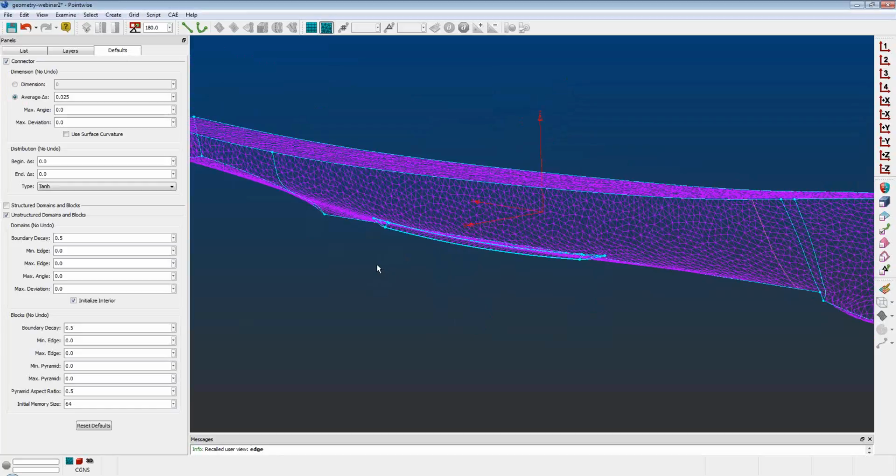So the general approach with our software, Pointwise, is, in this case, I actually have the default panel open in Pointwise. So what we do is we just say we're going to set an average spacing, or if you want, you can fix the number of points that are going to show up on the grid curves. And there's some more advanced parameters below, but for the most part, as a first step, you go ahead and fix your geometry, or maybe you don't fix it, you use the fault tolerant approach, but you put a mesh on your geometry, and generally as a first pass, it's going to be relatively uniform. Again, there are some advanced tools for creating non-uniform meshes, maybe based on curvature or something like that. Kind of similar to the question that Andy Liu was asking me before.